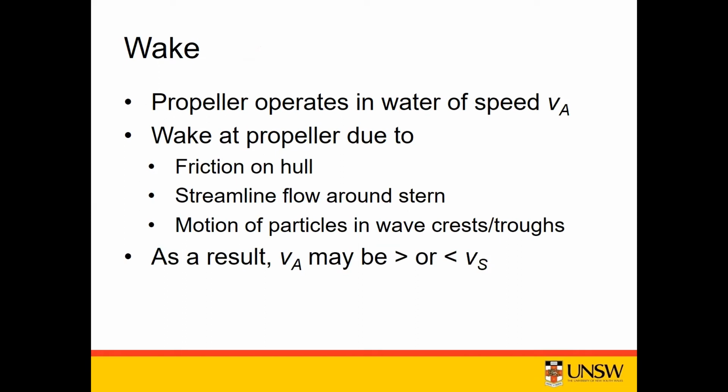When the propeller is operating behind a vessel, it operates in water at what we call the speed of advance. The speed of advance is usually less than the speed of the ship through the water, although it can be more. The wake at the propeller is due to the friction on the hull,